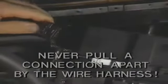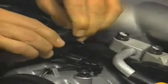Always release the retaining tab and gently pull apart by the connector body. Never pull a connection apart by the wire harness. When making connections, always be sure that terminals are correctly aligned, seated completely, and that the retaining tab is secured. Detailed information regarding connector servicing procedures is found in the service manual.